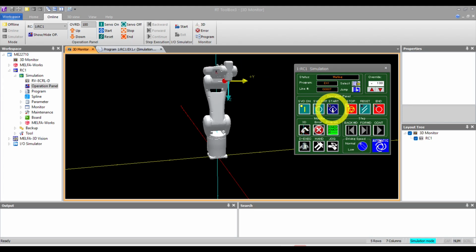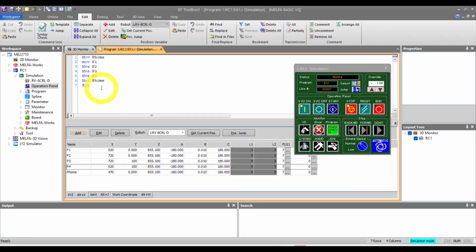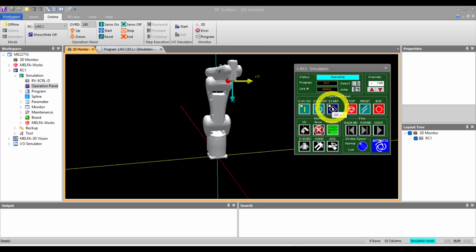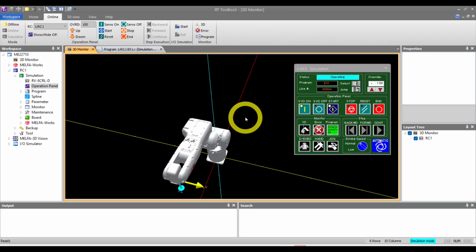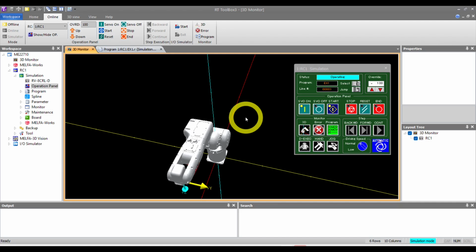Now the robot has moved. We just asked the robot to move 4 times. Now I'll do a minimum editing in the program. I'll come back and remove this halt. It will not execute yet, because we need to save it. So Control S to save. Now I'll come to the robot and press start. This is the simplest case of operating the robot.